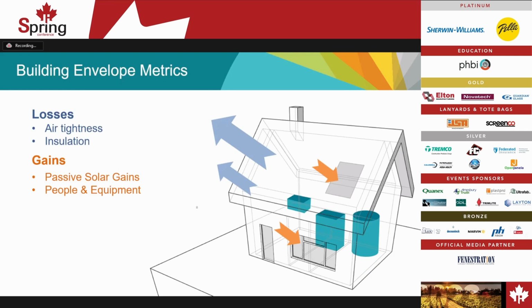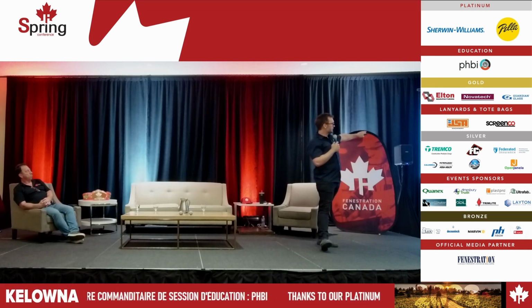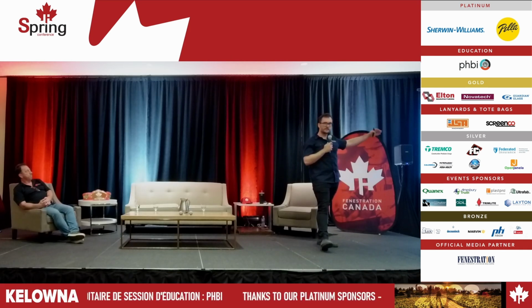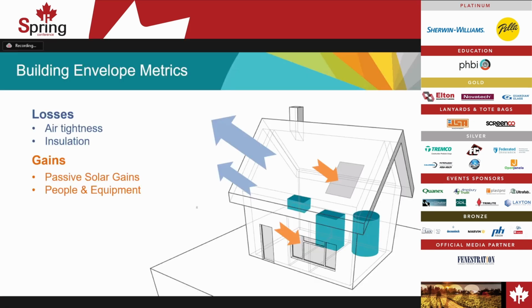For the building envelope metrics, we've got losses. So that's everything to do with air leakage, and then heat loss through the insulation, through the windows, in the basement. But we also got the benefit of gains, passive solar gains. That's that passive solar heating, right? So that's how we're orientating those buildings, what we're speccing for solar heat gain. Obviously, a higher solar heat gain is going to improve the energy efficiency, but we got to watch out for the comfort aspect in the summertime associated with that.